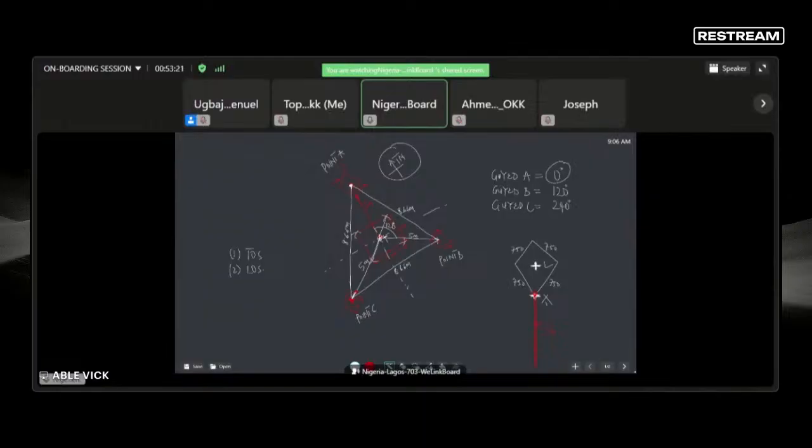But the issue is that different survey points were picked, and we had like 3 points that were fine for deployment with LOS okay, and maybe 2 points not LOS okay. Sometimes you have misinformation between the SAQ person and the survey team. SAQ might acquire points that are not LOS okay, and if you go there, you think you're on the right spot. You need to confirm that coordinate when you get to site.